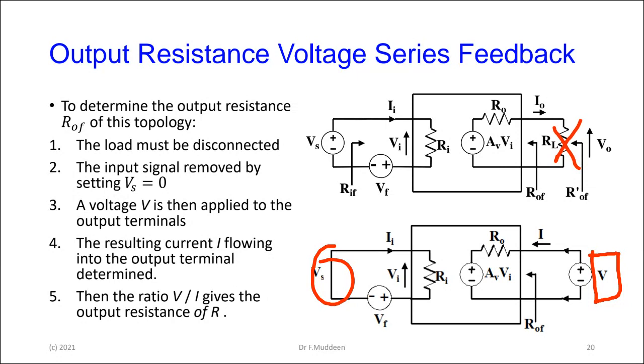So the same approach applies here. It's a little circuit, not your house wiring, but it's the same approach. If I want to see the resistance of the circuit from the output coming in, then I have to disable all my sources, of course, set them to 0, and then remove the load, because the load is in parallel with everything else. If I try to measure things, I'm going to get something in parallel with the load. I don't want the load in. Make sense?